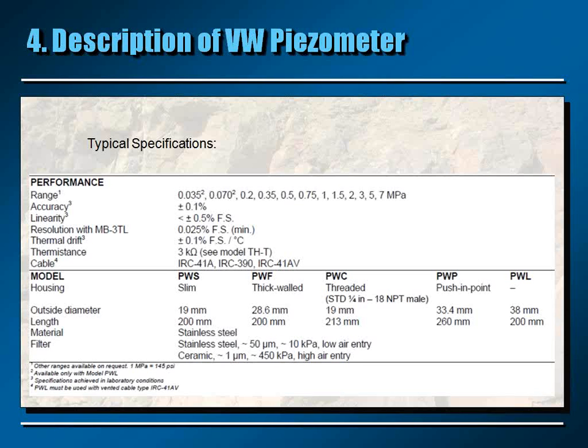And then you have the accuracy. The accuracy is obtained from a calibration. Every piezometer is calibrated here in the factory. This calibration consists in applying known pressure steps to the piezometer and simply reading the piezometer. And from these readings, we can obtain a trend curve that we can get by doing either a linear regression or a polynomial regression.